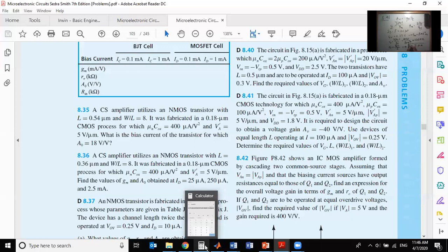Now if you substitute these values here, you should get L as 2 micrometers. Again, is this within the technology or not? The technology is 0.18, right? So it's not, it's bigger. This is the minimum length that this factory can generate. So if you ask this factory to generate something 2 micro, it will say that's easy, we can do this, but don't ask us to do anything below 0.18. What do we do if it is below? Then you have to either modify the design or find another technology, another factory, another place. But anyway, everything will be within this.